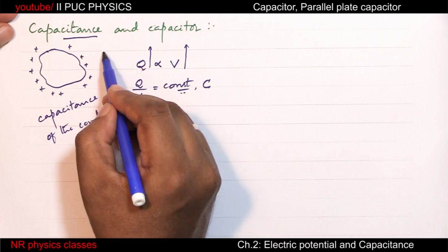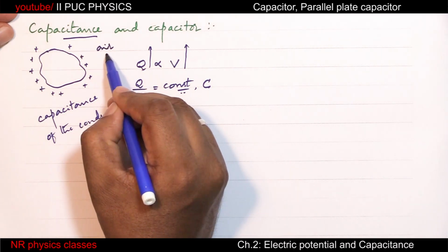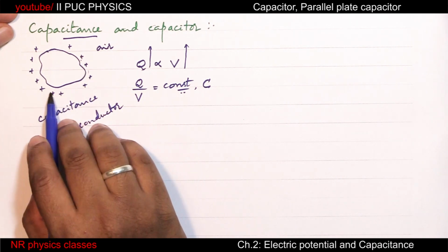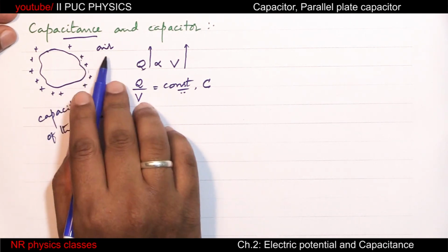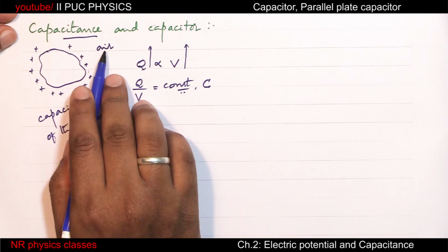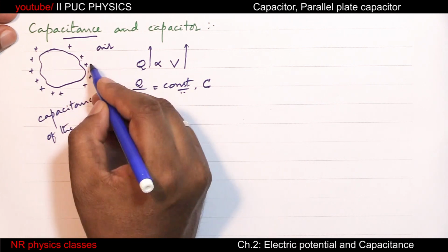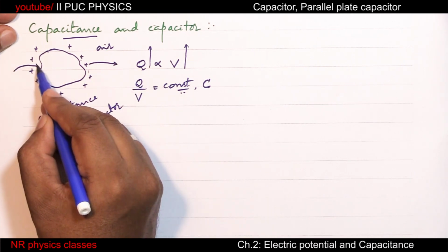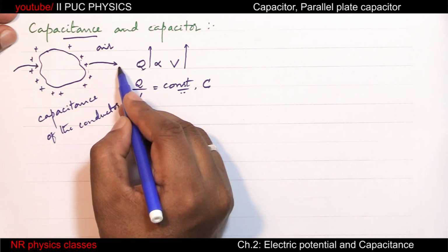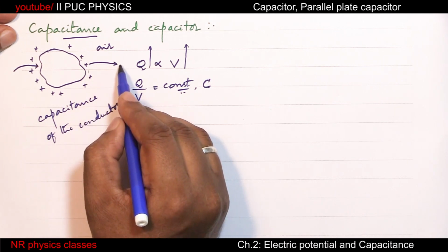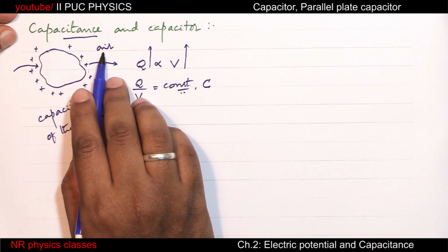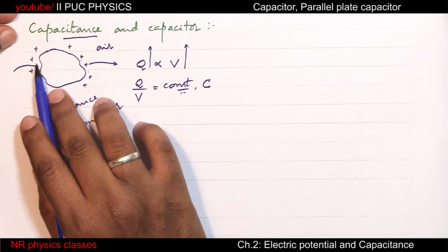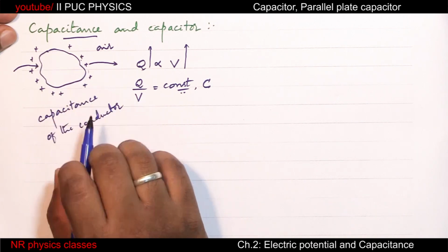As a result, this surrounding medium, which is air, is an insulator, this electric field, because of the charge, can break the insulating property of air. Once air loses insulating property, then there is leakage of charge. So we are trying to give charge, but there is leakage of charge. This leakage of charge happens only when dielectric property of air medium is lost. That can happen only when potential is very high, few million volts.